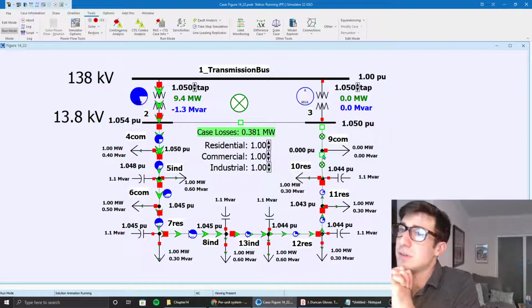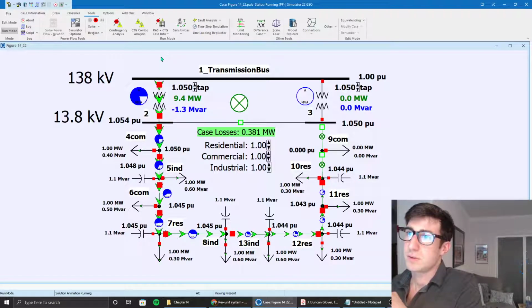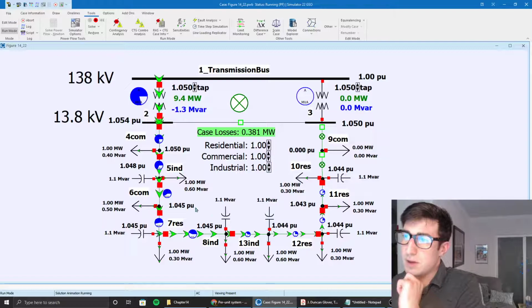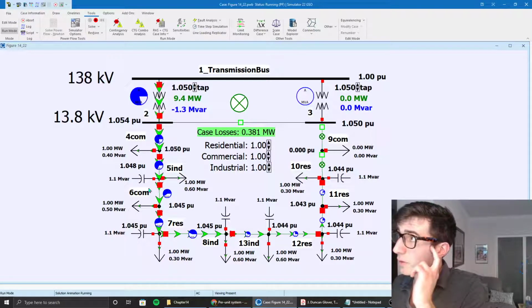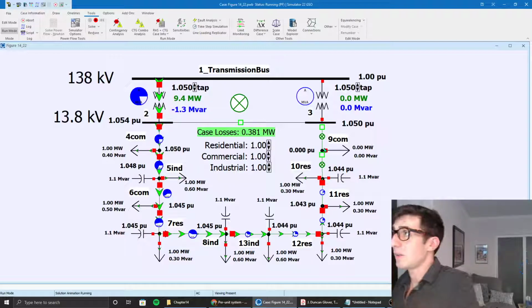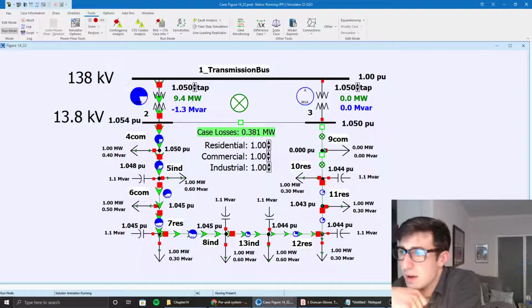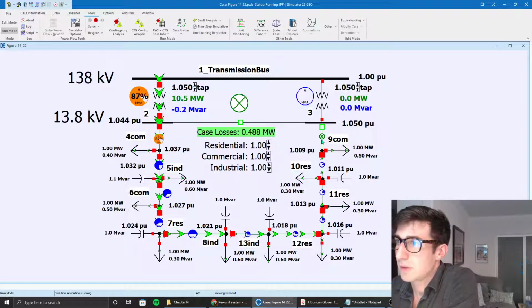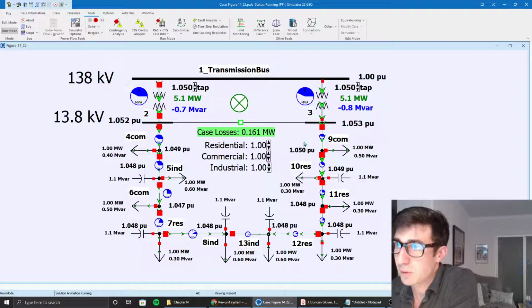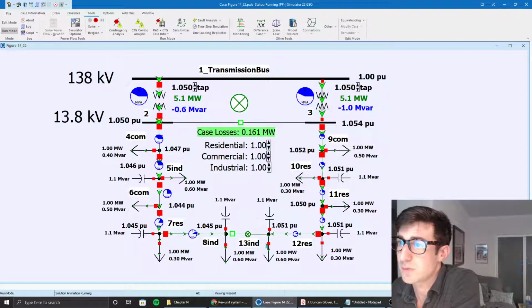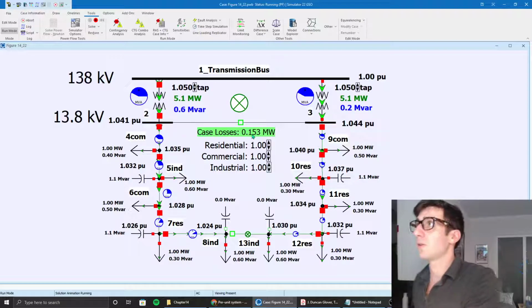because you have the dependency upon another line from the transmission bus and the distribution that's going to cover this area. And these are built with future considerations in mind based upon demands. And there are other things that you can look at within Power World to try to get this case losses to the lowest possible value. For instance, if you happen to remove some of these shunt capacitors, well, that removes the load, but if you remove a shunt capacitor here and here, I notice that it lowers the losses.